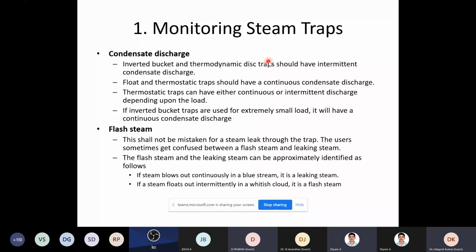See, one of the problems in the industry is everything is a quick fix solution. So you have steam going in, and then the trap is here. Okay. Now this is outside of the trap. Now what normally you will find, there is also a bypass with a valve. This bypass system is provided to the trap. When the trap fails, you open the bypass.